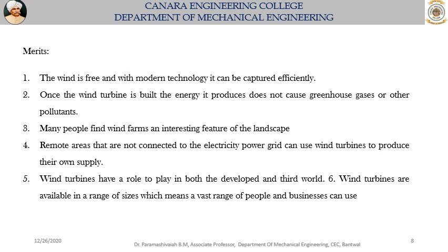In remote areas, in rural locations where there is no power grid available and no power lines are drawn, we can install the wind turbine directly if wind is available, because there are some conditions. The wind velocity should be a minimum of 5 meters per second and above, and it should be available in almost all seasons or days of the year. Otherwise, it will be a problem.